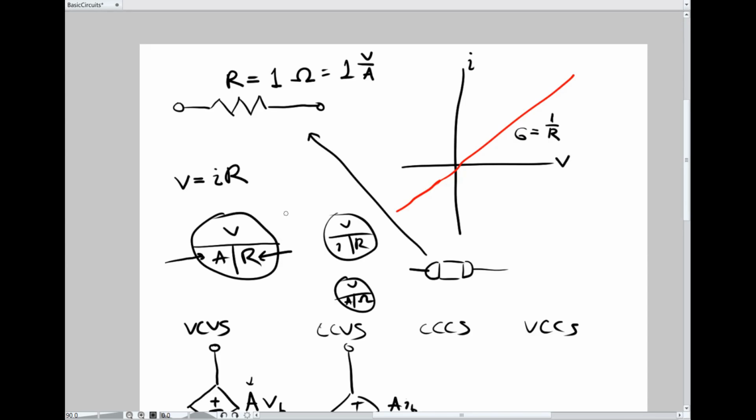The only case I could think of where you might encounter a negative resistance is if you are finding the Thevenin equivalent resistance of a circuit with a dependent source in it, and specifically circuits with dependent sources in them that are just solved as an academic exercise, right?